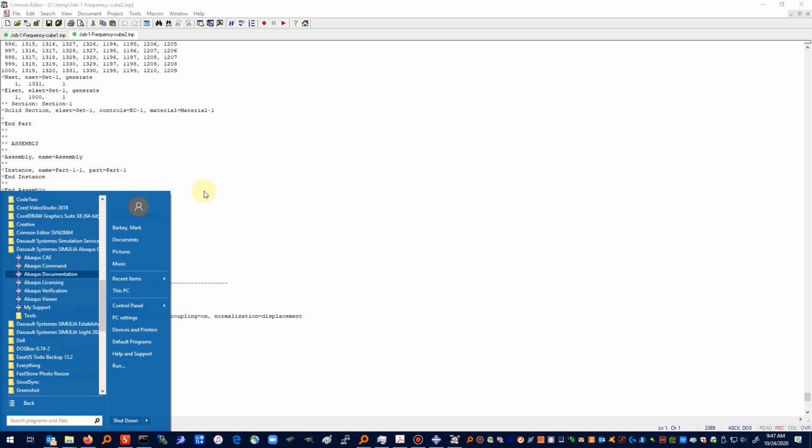Hourglass equals enhanced. Default for elements with hyperelastic and hyperfoam materials. Default for standard, and only option in ABAQUS/Explicit for modified tetrahedral or triangular elements. Okay, to define, Hourglass control is based on the assumed enhanced strain method for solid, membrane, finite strain, and all this. Any data given on this data line will be ignored for this case. Alright, so all these different things are options that can be used to tweak your Hourglass controls.